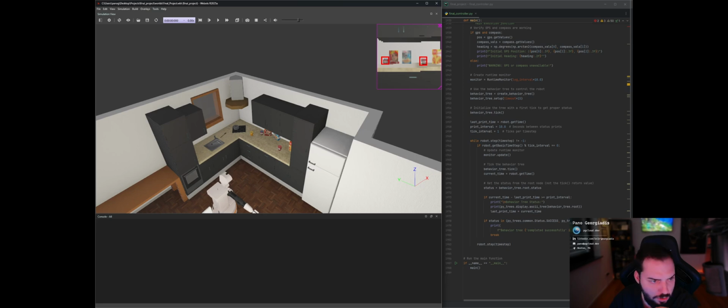The grasp success rate is at 100% because we have not only the first grasp check, but we also have a lift and verify check as well. Our navigation accuracy is plus or minus 0.08 meters. Our path efficiency is around 90% for displacement over total distance. And then we have that force feedback consistency for the gripper fingers, pretty much consistent across the board for each jar. The controller demonstrates reliable operation across multiple test scenarios with successful detection and transport of all 3 jars.